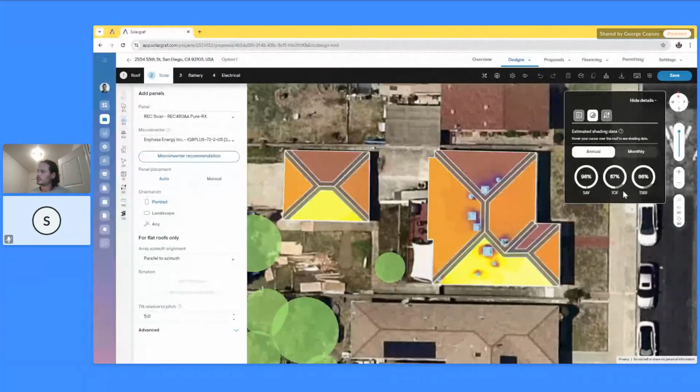Now, the last thing we look at is called TSRF, or the total solar resource fraction. And to do this, all we do is multiply SAV and TOF together. 2 percentages multiplied together equal a new percentage. And that really is the best metric that we can use to determine how suitable any particular part of the roof is for solar production.